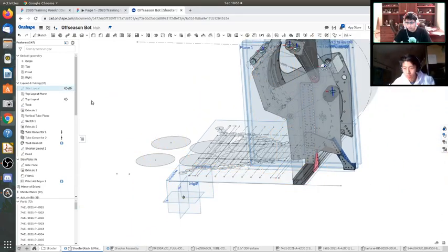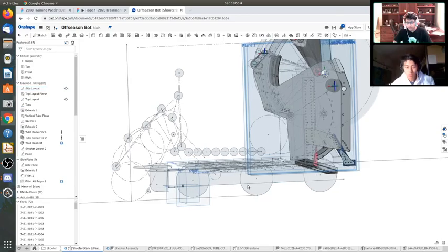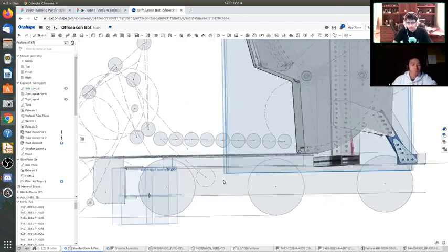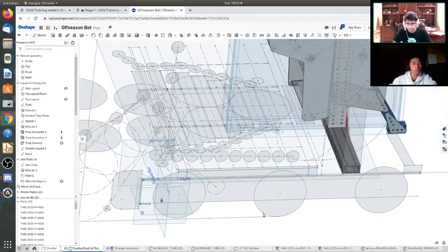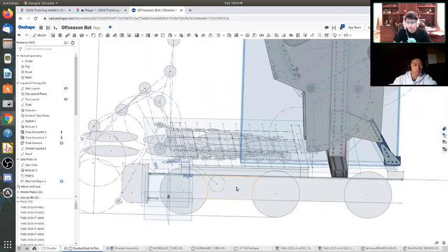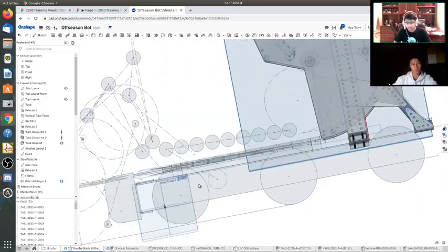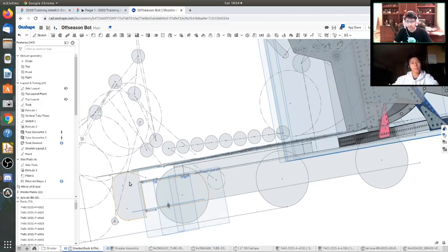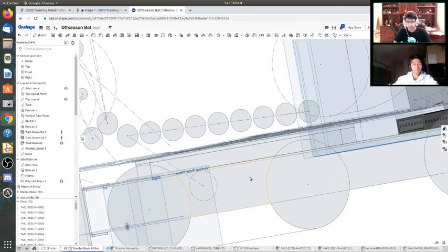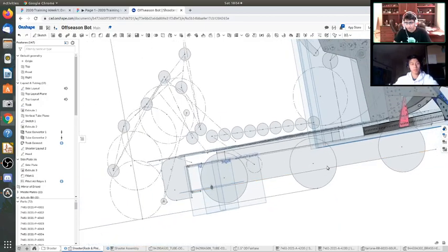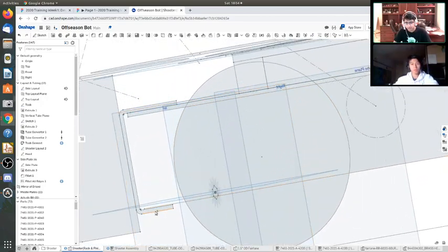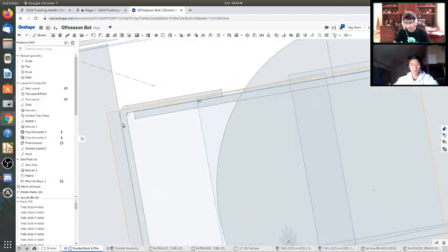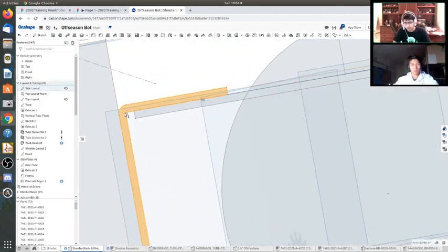So what we do, and admittedly we found better methods, which I'll be covering in a future video, is this pretty old layout sketch, a couple months old. The method I like to do now is to derive the parts into my part studio and then build everything up around those derived parts. But what I used to do was create a part studio in context, make a sketch on the face of the drive rail, and then use the convert entities feature to project all of these. So I literally convert entities and click on this face right here, which projected the entire thing.